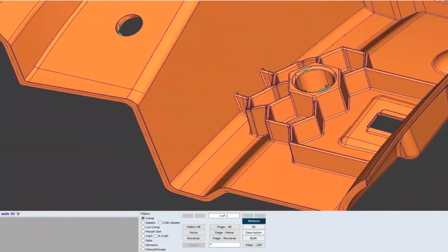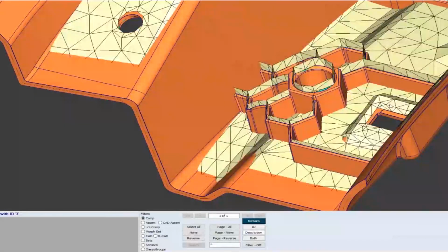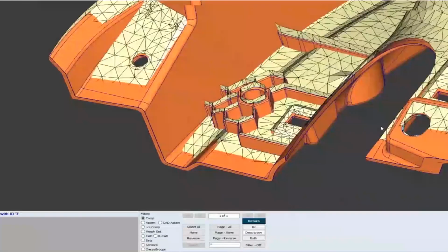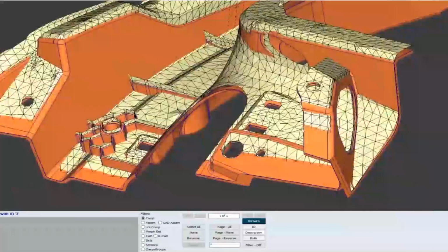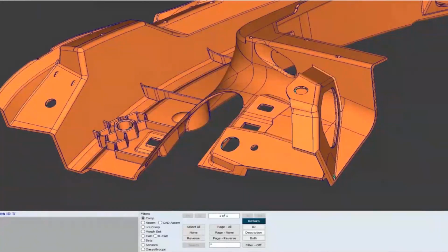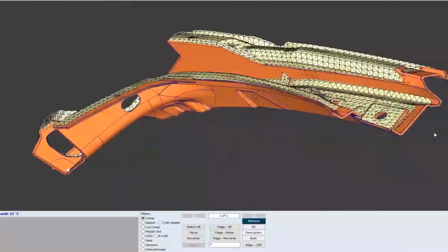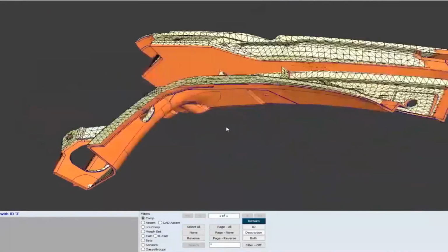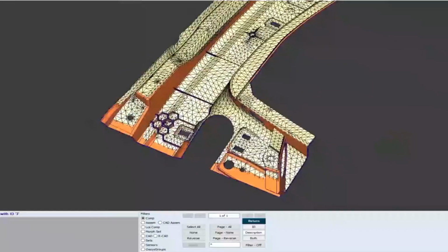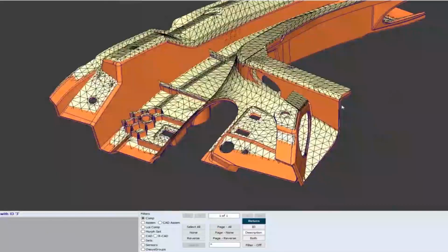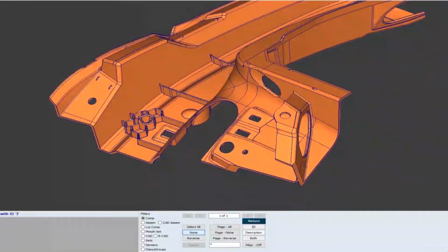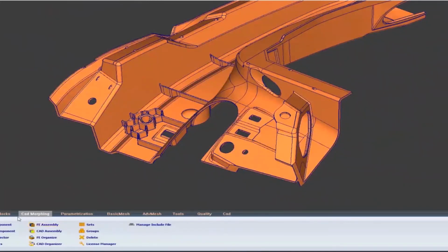And now I will show you the warp mesh. This would be the warpage corrected mesh, which we can export from the previous window. I can zoom, I can just rotate the model just to show the complete model. So if we have the nominal mesh, nominal CAD, and the warpage corrected mesh or the warpage compensated mesh, then we can go in CAD morphing.